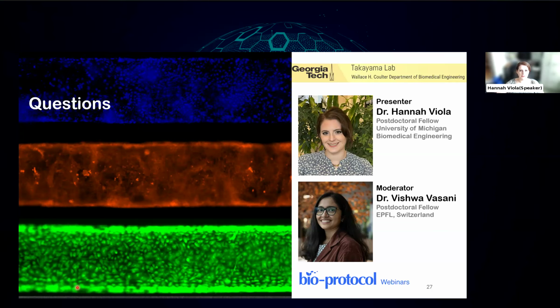Maybe it was a collision, maybe you were just cutting and then it broke. That means maybe that particular cut needs to be optimized or run more slowly, or needs a different set of spindle speeds or a different size. But there are so many variables, and it's just kind of trial and error when those things happen. And if your cut is going to be 14 hours long, you don't have time to sit there and watch. Some microscope cameras do record, so you could record a video and come back and look at it.